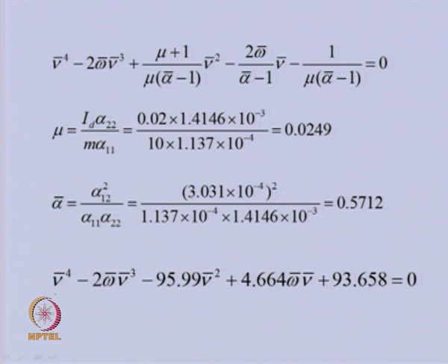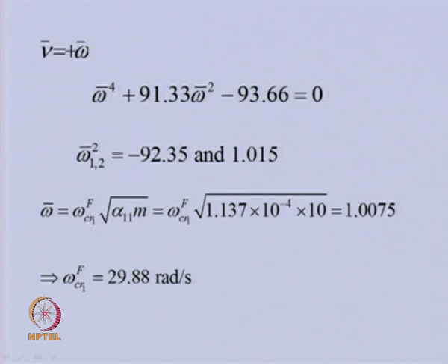If we recall from the third lecture, when we considered the general motion of a disc, this was the frequency equation we got, in which we had the spin, the non-dimensional spin ratio, coupling effect, and disc effect. These can be calculated for the given values, and if we substitute them in this frequency equation, we will get a polynomial like this, which is the frequency equation.